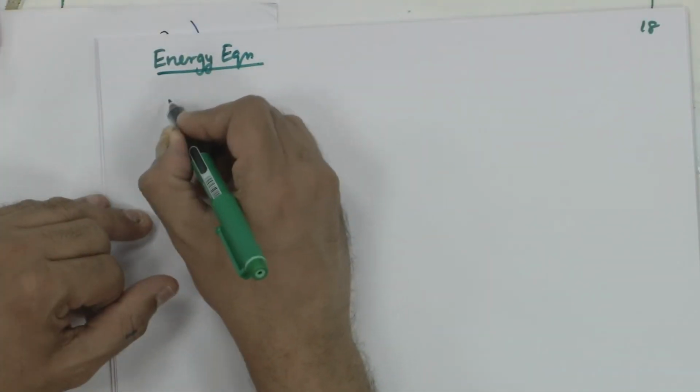Okay. So once we have understood the definition of enthalpy thickness, we will just get started with the derivation of the integrated energy equation. Your integrated energy equation follows the same logic as the derivation of the integrated momentum equation. Now you are dealing with two boundary layers, delta and delta T. The H that is chosen is greater than the maximum of delta or delta T. So we do not have to worry about it, and your integrated energy equation is going to be obtained in this manner. Boundary layer approximations were introduced already.